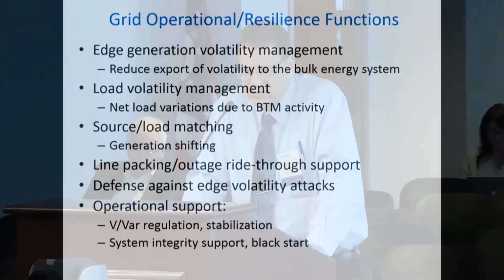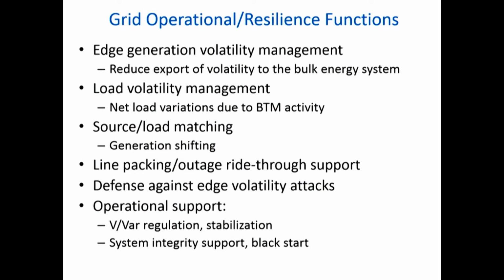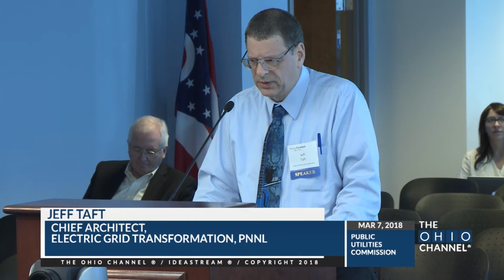So you can actually think of this, in addition to everything else, as a kind of defense against that sort of attack. And then, of course, using it for operational support for the things that you need to do just to make the distribution grid work well: volt-var regulation, stabilization, support for system integrity, even black start. The APPA folks have a report out now on the use of storage in their utilities, and one of the examples is using it for black start. So there are a variety of things that you would just consider operational issues and resilience issues that this can apply to, in addition to supplying the services in a way that people usually think of, and in addition to the behind-the-meter functions that people would use it for.